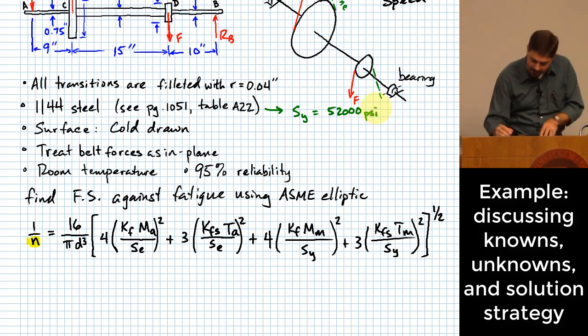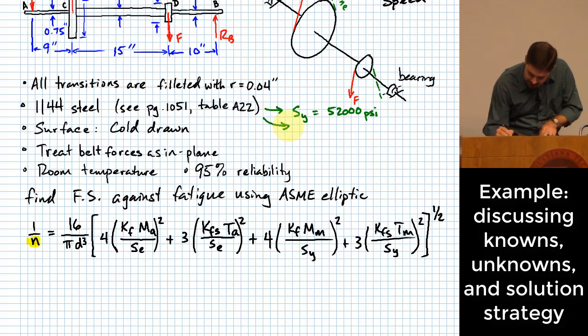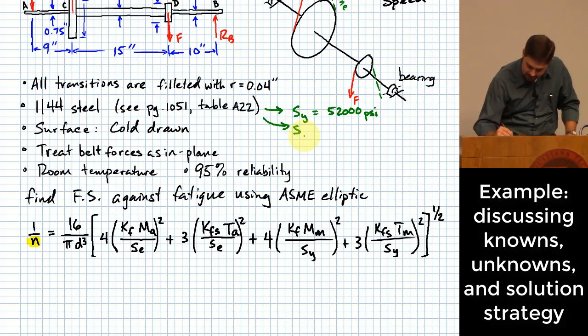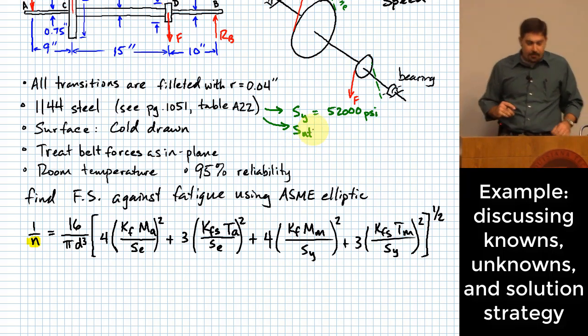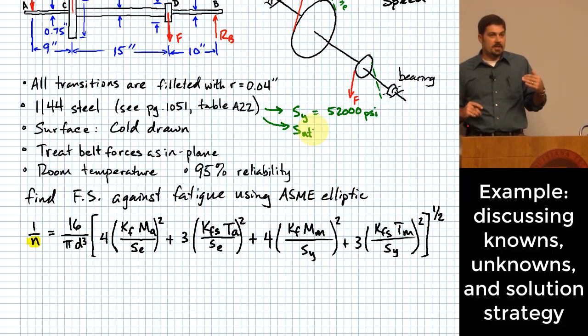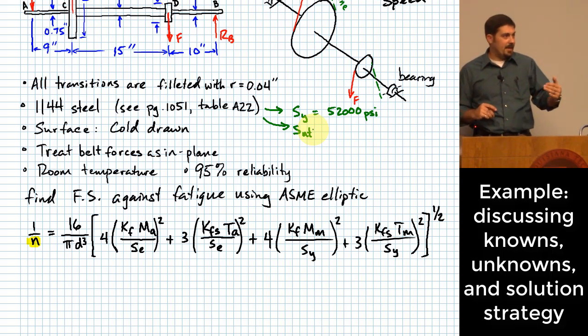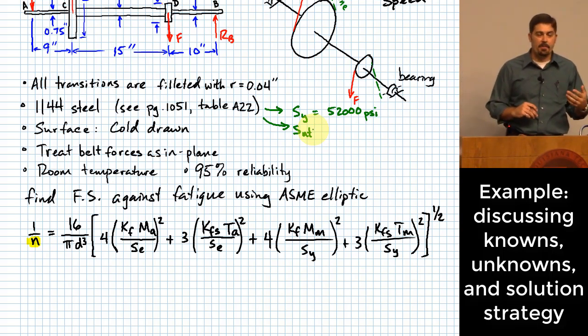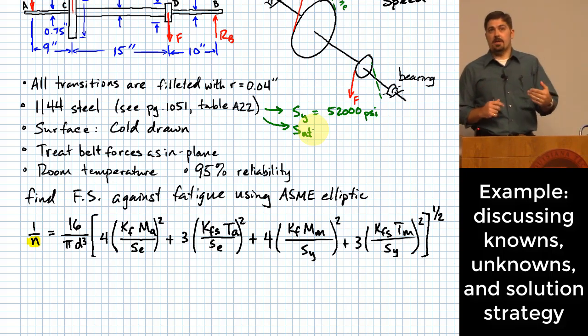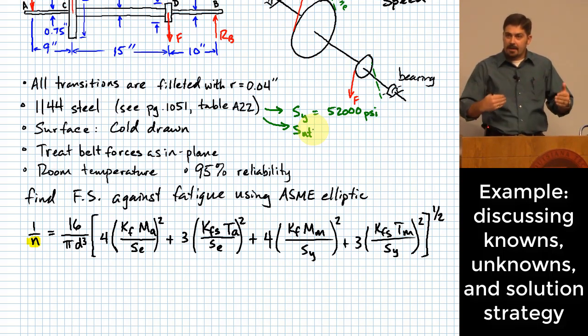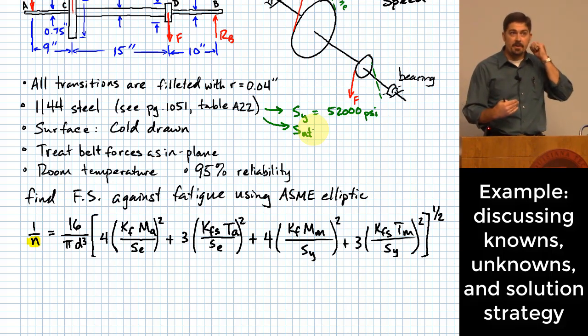The other property we're going to need in just a second is what? In order to find the endurance limit, we have to go through a process to find it, unless it's directly given for some reason for a certain type of material. That process generally involves correcting an endurance limit for all the factors we have to take into consideration.